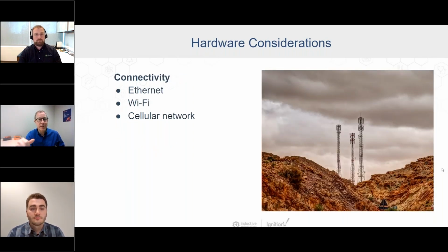And then I think this is my last slide, connectivity, and connectivity is huge. It's one thing to have the data, but by goodness, you better be able to get access to it. Industrial atmospheres, noise, electrical interference, all those kinds of things. Hardwired Ethernet will always give you the best results. But there's plenty of places where it's just not convenient to get wiring to. Wi-Fi is going to be the key thing for you to be able to get to that stuff.